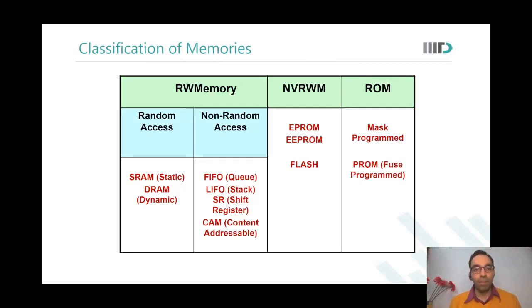What is that actually? What does that mean? Suppose my chip is manufactured in slow lot. I now want to operate this particular chip or this entire lot at 1.14 volts instead of 1.1 volts, so that I get the required frequency. This is a one-time programming that you will do in the fab by blowing away some fuses. This is not about storing a new set of instructions or a particular set of instructions. Is that okay?